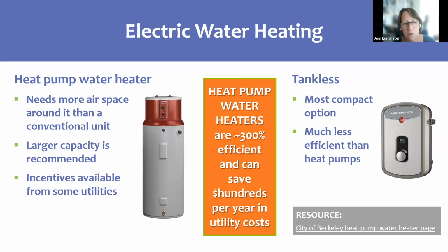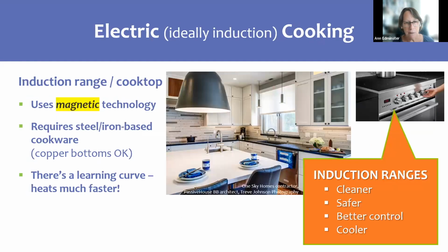There's also one model of split heat pump water heater, that's the Sanden. What that has is the compressor unit lives outdoors, and then the tank portion lives indoors, or it can be in a garage. That's by far the most efficient, and also has the lowest global warming potential of any of the refrigerants used in the heat pumps that facilitate the heat exchange. So several options to keep in mind here.